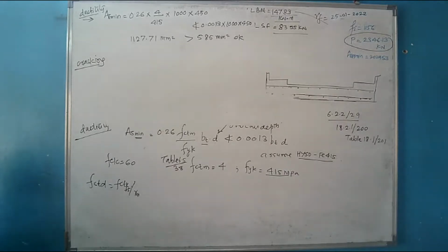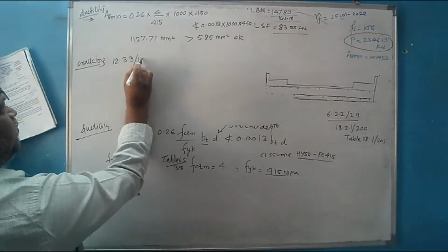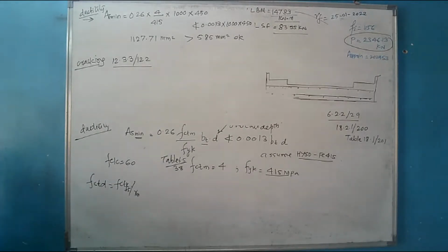अभी हम क्रैक विड्थ के बारे में बात कर रहे हैं. So for this crack width, or for the minimum area of steel to avoid the crack, please refer to clause 12.3.3. It is available on page number 122. What does it say? ऊपर जो दिया है Table 12.1, अगर आप रेफर करते हो तो that is about what is the maximum size of crack that is permitted. That is mentioned there: moderate condition, severe condition, very severe and extreme condition. So what are the maximum possible crack widths permitted, those are mentioned there.